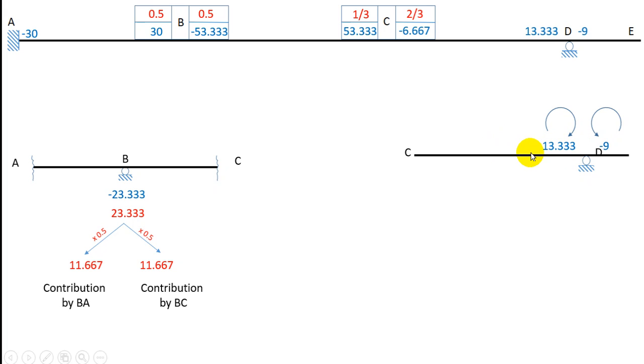First I'll make this 0. You can see here it has now got displaced because there is an unbalanced moment. So I'll make this 0 by providing minus 13.333. This minus 13.333 was earlier given by the beam itself, but the pin joint does not have any strength to provide this moment, so as structural engineers we provide it, and we have to carry it over.